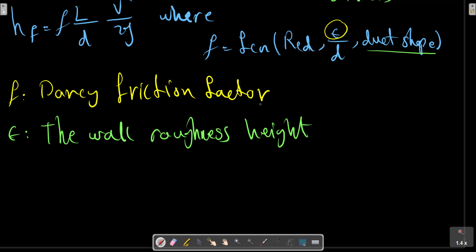By the previous equation, we find an alternative for the friction factor, such that we can write f equals 8 tau wall over rho V squared. For non-circular ducts, we must interpret tau wall to be the average value around the duct perimeter. For this reason, it is preferred to use a unified definition of the Darcy factor.